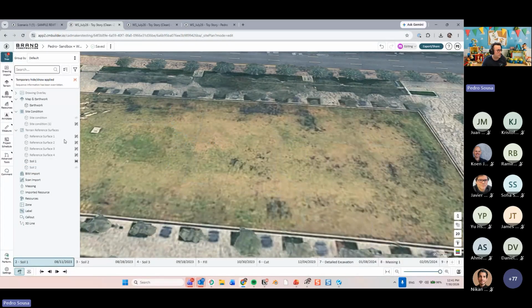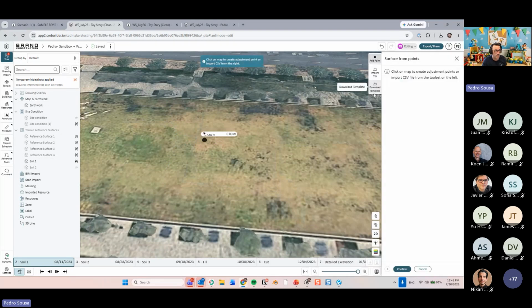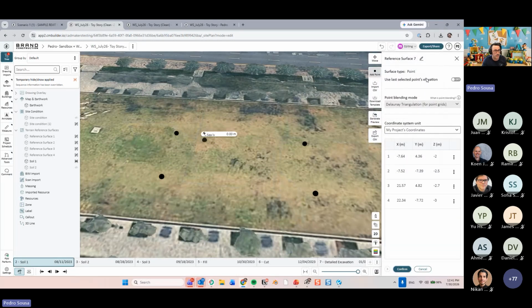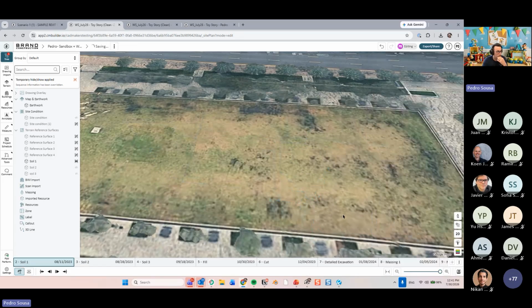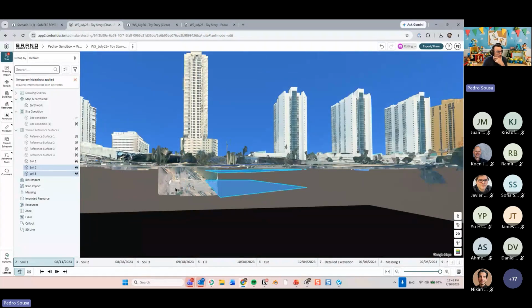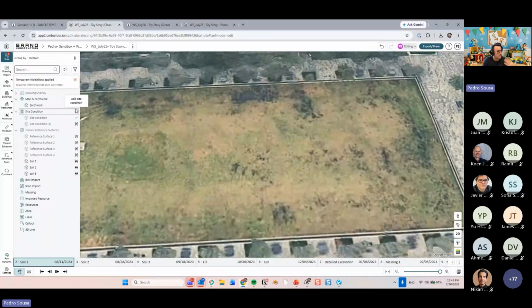And the last one, just so we can finish this example, I would do that very quickly, and I'm going to create another soil 3, and I don't remember the other values that I put, so I'm going to put everything into -6, which I think was the lowest point for everything, and -7 on this one. Okay, so now I have all of those 3 surfaces created over there, and then I can go and create my cuts showing that.